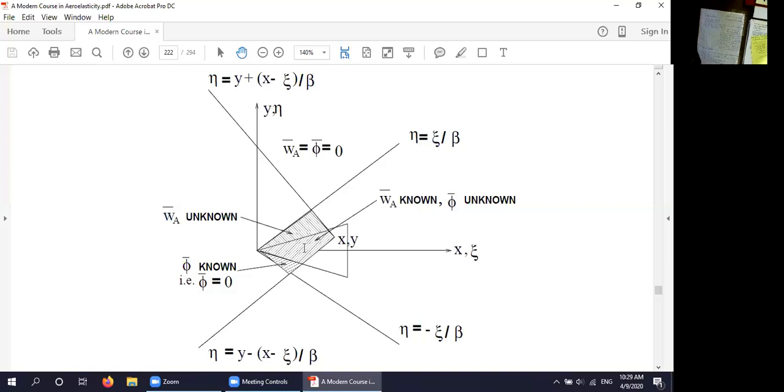And so we have to do some linear algebra. We have to do some manipulation to make sure all the knowns are on one side and all the unknowns on the other side, but we can do that. Taking into account also the singular nature of the solution along these Mach lines, and these Mach lines are where that square root singularity occurs. So that's it. You've now become experts, at least in the formulation of 3D supersonic flow.